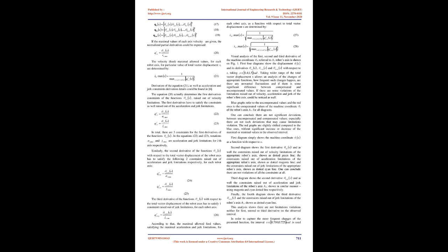The method for calculating the compensated machine coordinates after the parametric robot calibration procedure, for a given particular desired point in the pose space, is described in detail above. In practice, when a 6-axis industrial robot, or even a more complex machine configuration, is used in composite tape laying, it is controlled by machine coordinates.